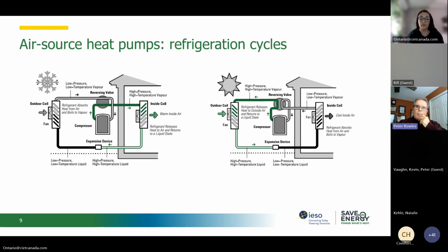The heat pump uses a compression, condensation, expansion, evaporation refrigeration cycle, similar to refrigerators. It allows heat to flow in directions that it wouldn't normally naturally flow in a straight heat exchange situation. An air source heat pump will have two coils, an indoor and an outdoor coil.